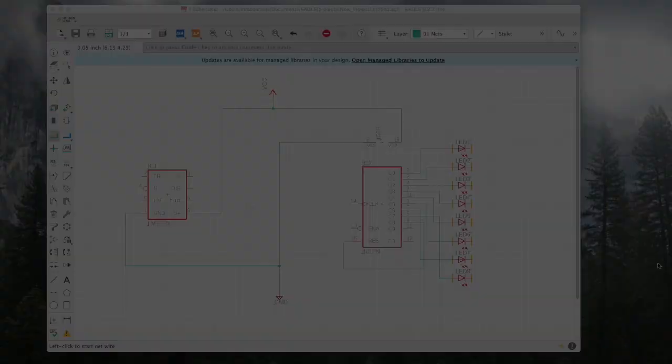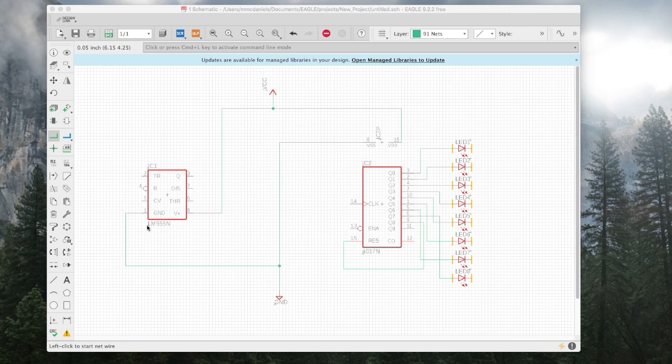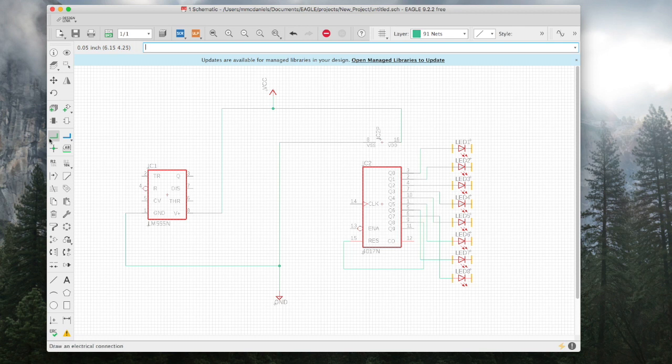So why don't we go over the circuit design right quick using Eagle design software. Here we have it. I'm well on the way with a 555 timer schematic and a 4017 decade timer. What we're going to do is use the 555 to generate pulses, probably around 10 a second, or a pulse every 1/10 of a second, and that will cause the decade counter to go from the first line, powering the first LED, down in sequence through all 8 LEDs.